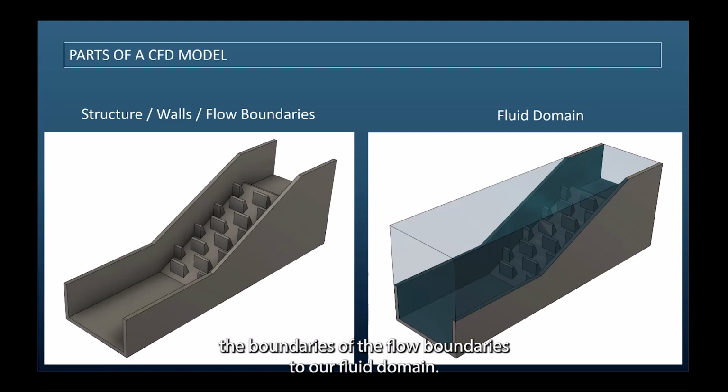to our fluid domain. There are cases, however, where you may want to include, as in this picture, both the fluid domain and the solid region, and that is if you were, for example, interested in solving for the temperatures in this concrete region as well, then it could be included in the computational model as well. So with that said, let's move over to Cradle and take a look at how to build this simulation model together.